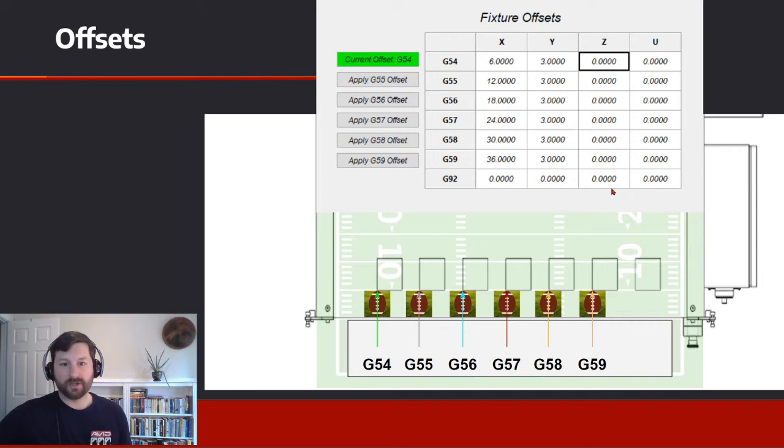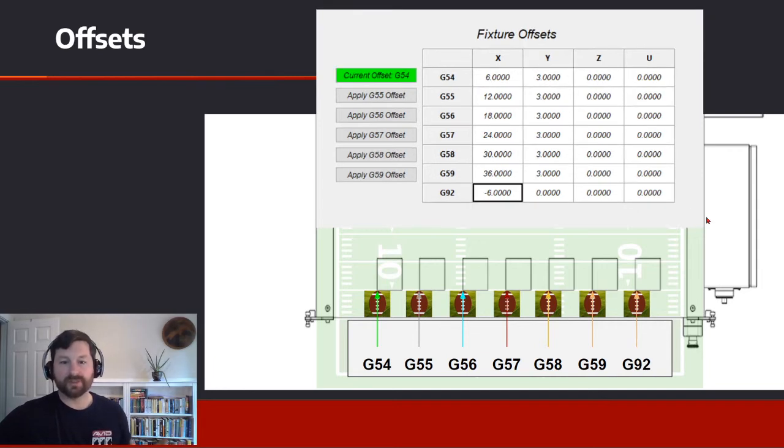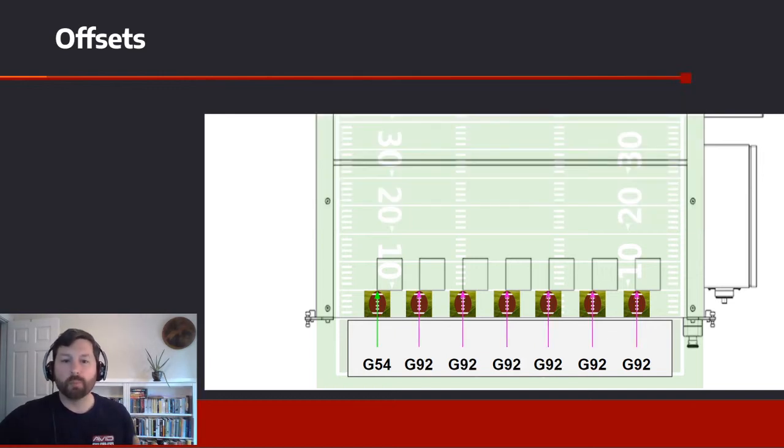And so this is another thing that Lars and John both touched base on, but this is a G92 offset. And a G92 is a very special offset because it essentially says, hey, whatever your position is now, I am resetting that live in the G-code. And so within your G-code, theoretically, you could have multiple G92 commands.